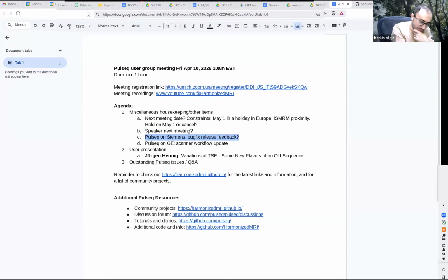But that's on the ADC side. On the ADC, I noticed it's getting very tricky to use dwell times below 2 microseconds. It's possible, but tricky. Not all combinations are possible. My feeling is that well above 2 microseconds, the system allows you pretty much everything which is divisible by 100 nanoseconds in terms of a dwell time, and also pretty much any number of samples if it's divisible by 4.